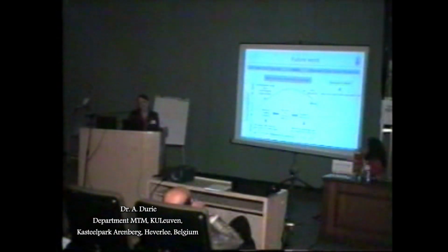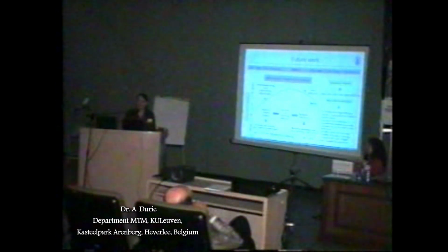This work was done on a hand-built loom that we built as part of a PhD program. And now we're looking at getting this work into a production loom. So what we have to do is look at whether or not we can use other existing applications to provide warp crossing. The problem is that the number and the complexity of the parameters increases every time you increase the architecture of the pile. There's obviously changes to the timing and all of that sort of thing that we have to do anyway, and compensating for the path length of each of these. So every time you make a design change, you have to incorporate that into the loom. That's normal, I think, for every textile process.